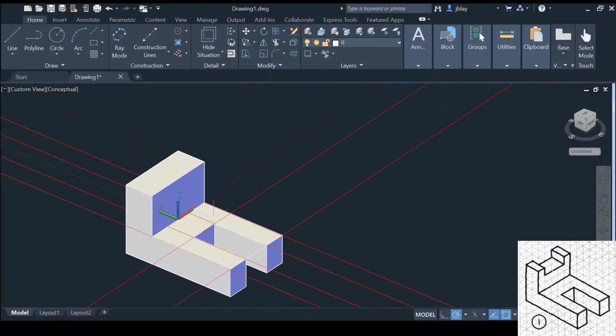You also alternatively could have used a rectangle, which probably would have been a little bit faster, but we are where we are now. Okay, now let's work on this top section and do a similar thing with our construction lines. Let's take a look. It looks like it's 1 unit in each direction. We have the start of this intrusion. 1 unit is 1/4 of an inch. So let's again do some construction lines. Do one here. And then another one at the other end.